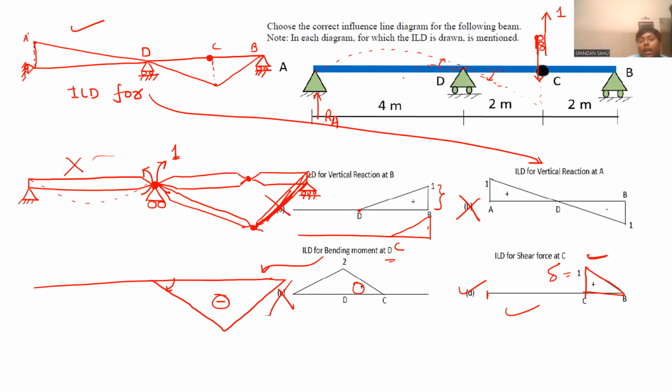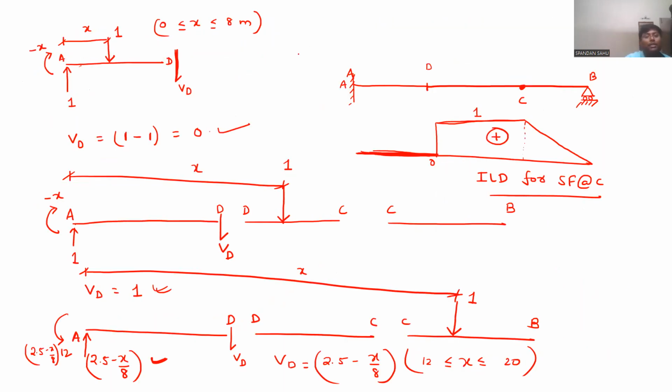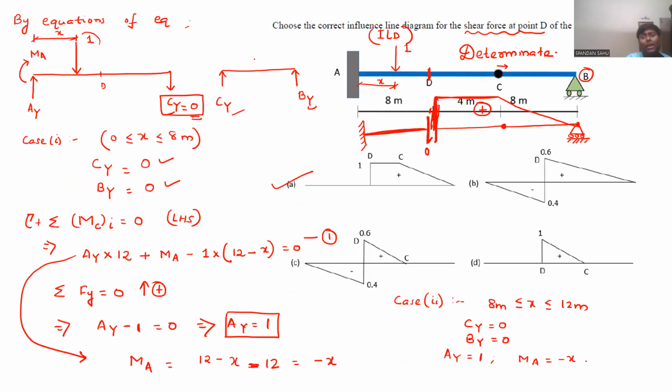Now, whatever stress function ILD you want to determine, once you are done with all those things, at which section you want to determine the value, you go to that section and cut that section at that point. The stress function for which you want to draw the ILD, like in the previous case, for shear force, we have to draw the shear force ILD at point D.